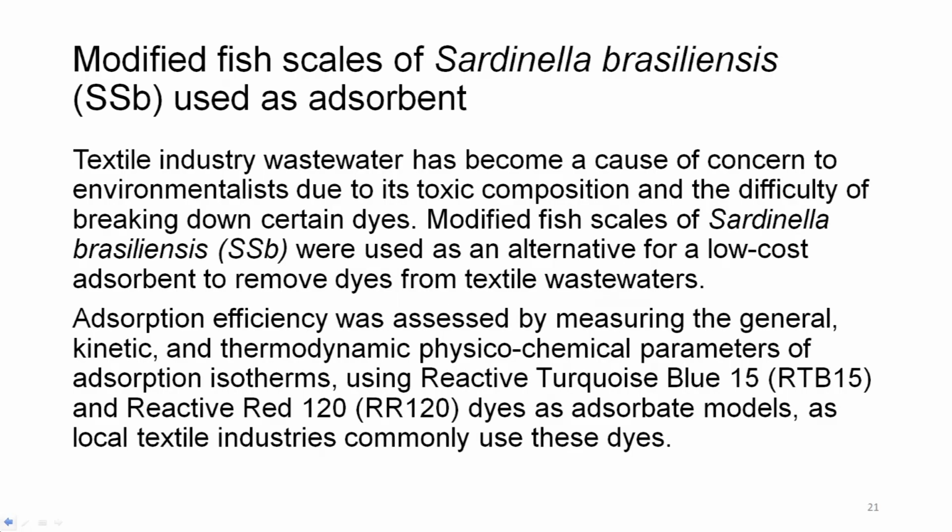Adsorption efficiency was assessed by measuring the general kinetics and the thermodynamic physicochemical parameters of adsorption isotherm, using reactive turquoise blue 15 and reactive red 120 dyes as adsorbate models, as the local textile industry commonly uses these dyes.